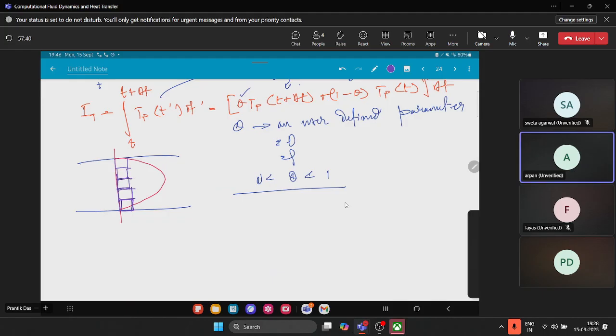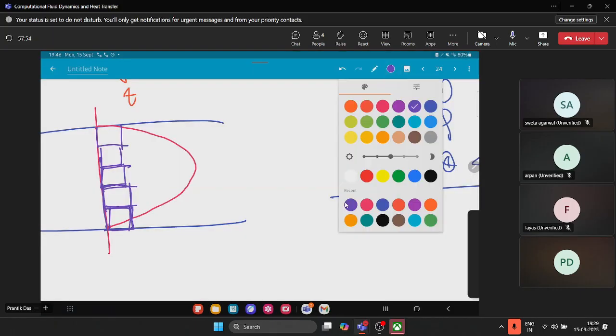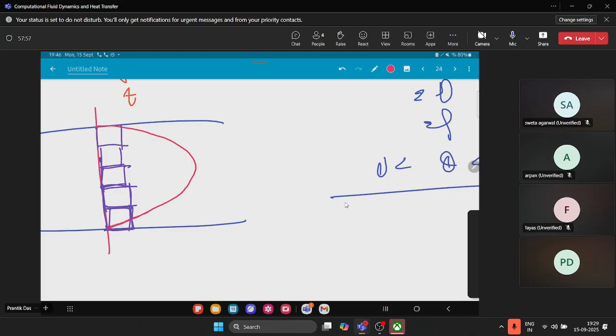The velocity, the pressure, the mass flow rate, these are the things which will come in to be inaccurate. So what you will do is basically first you will see the contour here. There will be some problem with the contour itself. If I plot the profile in my CFD solver, then I will see that it is not coming to be parabolic, it is coming to be linear. Then I will understand that some issues are there. I will find out the stress. It is not tallying with the analytical solution itself for a flow through a pipe. Then I will understand that the stress itself is inaccurate.